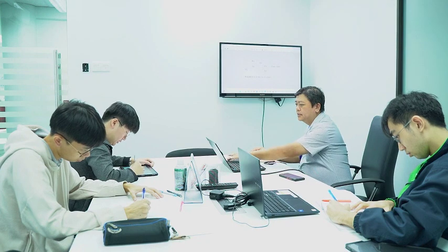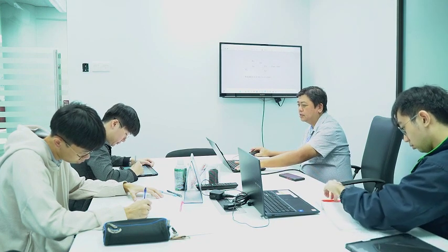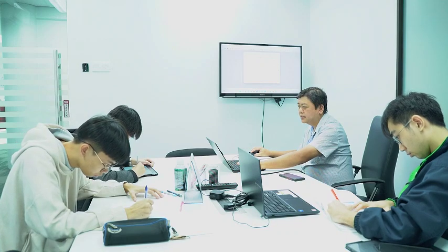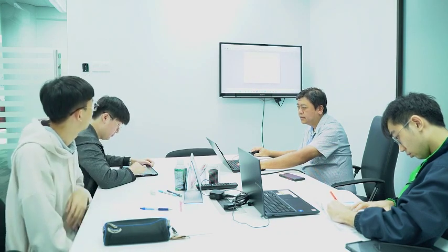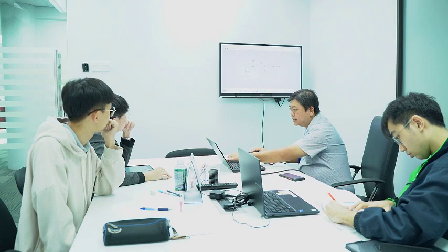How do we do the simulation? This is the RC filter. You change the 1 to none here, and put AC 1 here. Now we run the AC analysis.